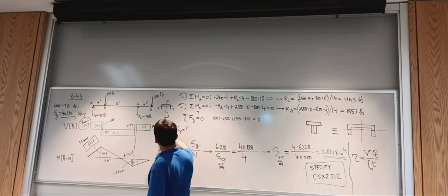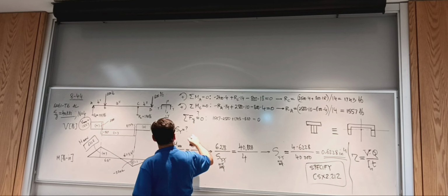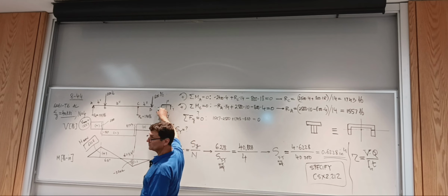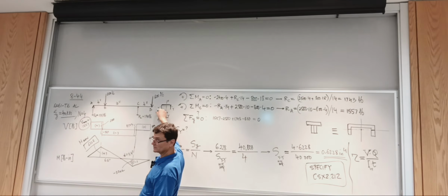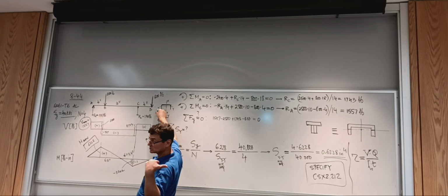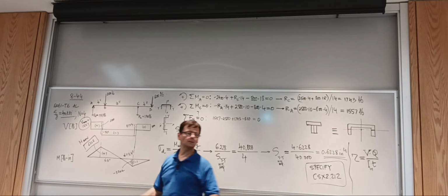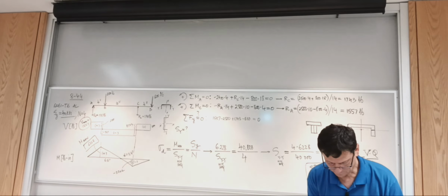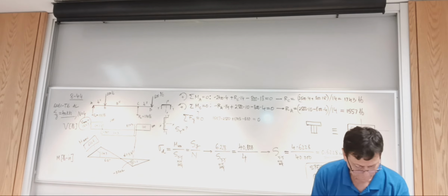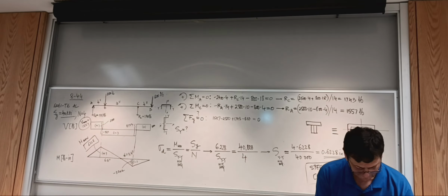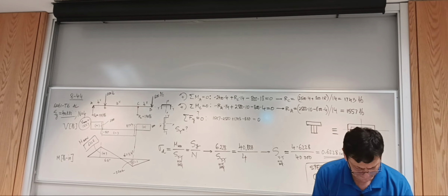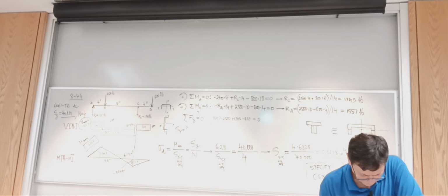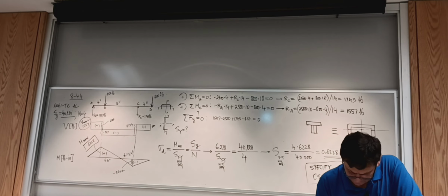Of course, a channel oriented this way versus an I-beam, the only difference is that when you place the loads, they need to be through the flexure center. And it's a section that we covered. We have the equations for the rectangle. Yes, we have T sections documented.